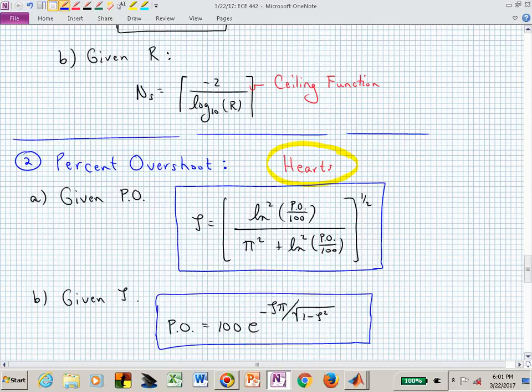And when are these really true? This is really just sort of rules of thumb. These are for second order systems. Pure two-pole systems, these zeta and percent overshoot values correlate via that formula. Or if you're given zeta, if somebody says, oh, I want a zeta value of 0.7, you know what that percent overshoot is, but you could compute it here, and you should find that it's 5% from this formula. That's the second performance specification.